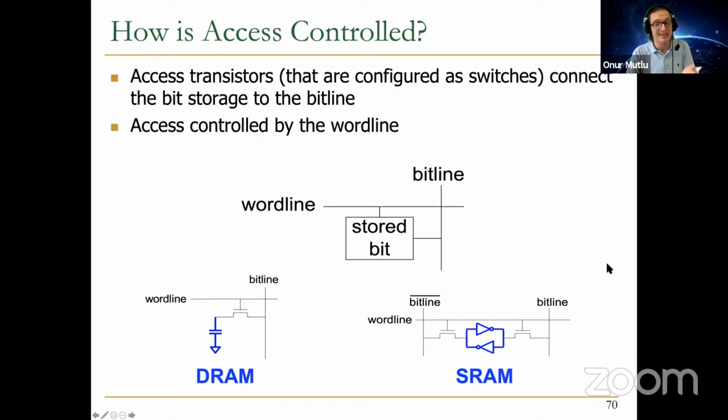Now you have 2 bit lines in this particular SRAM implementation, a bit line and a bit line bar. And there's some sensing circuitry at the bottom over here that does differential sensing of the bit lines so that you can get a more robust reading. So you basically sense the difference between the bit lines, and having one bit line highly charged and the other one oppositely charged amplifies, making it faster to do the sensing essentially. That's why you look at bit line and bit line bar. But this is one example of reading circuitry. You can certainly build SRAMs where you just look at bit line or bit line bar, basically.